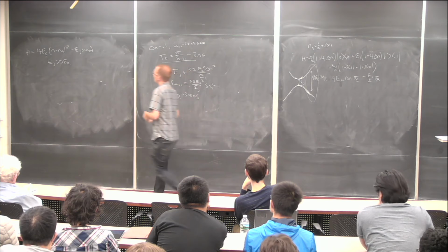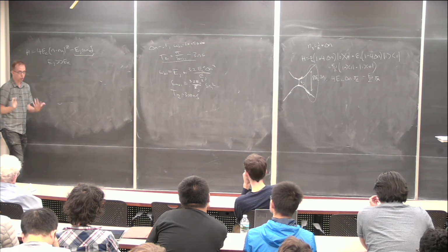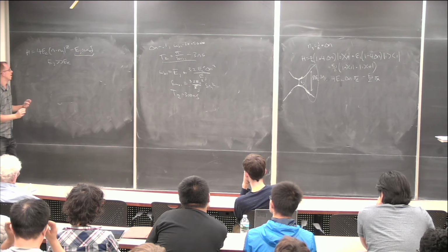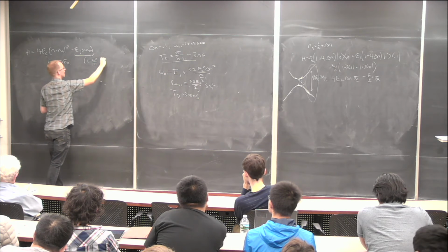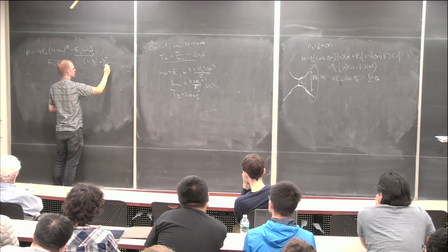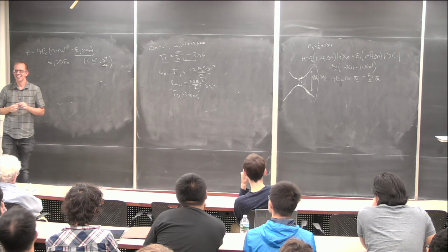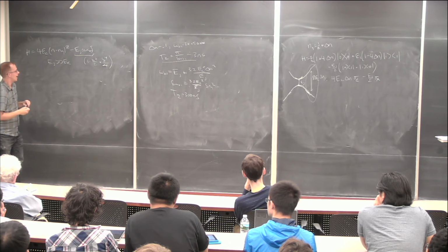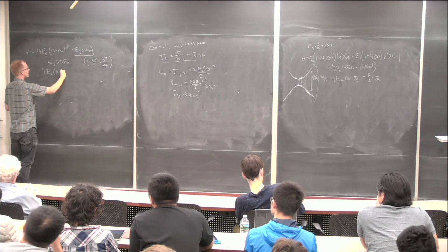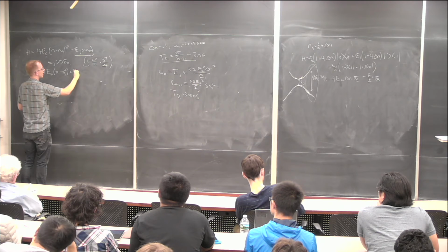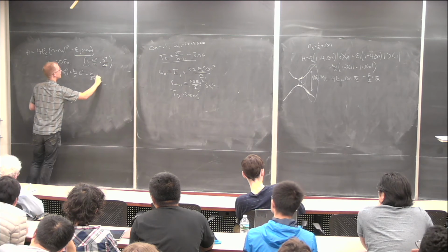And so, as you do this, you are entering the limit where this thing really looks like a pure nonlinear inductor, and you can treat it as 1 minus delta squared over 2 plus delta to the 4th over 24 kind of term. You can really just Taylor expand this, and this becomes an energy offset. So it winds up being 4 EC times (n minus nd) squared plus EJ over 2 delta squared minus EJ over 24 delta to the 4th.